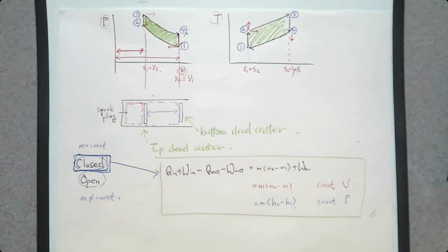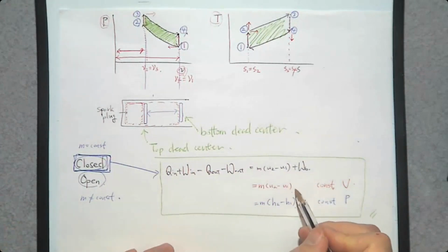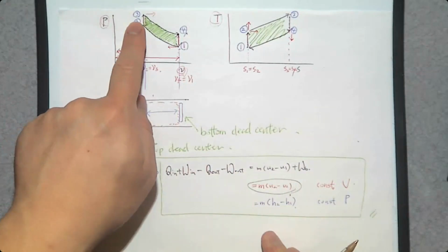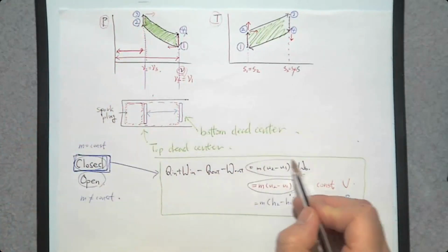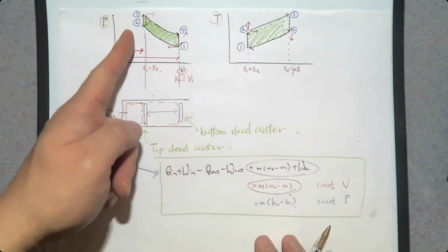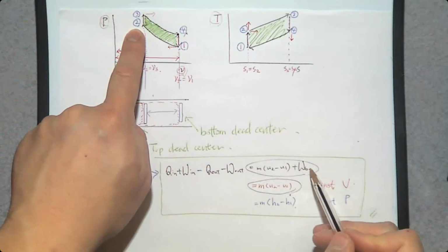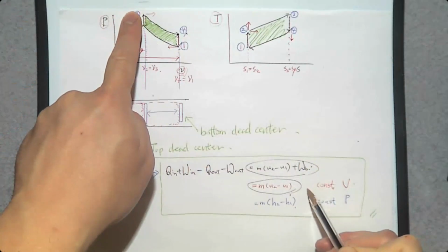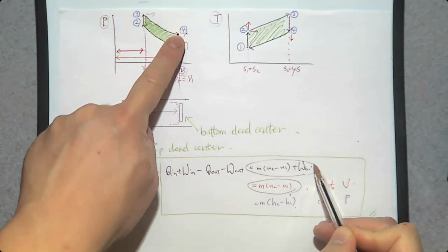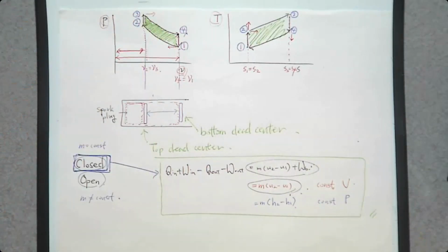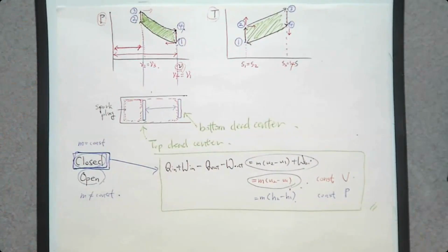So in this case, we have a constant volume process between 2 and 3, and a constant volume process between 1 and 4. So we can use this one for the constant volume process, and this one for the isentropic process. So between 1 and 2 is going to be this one, between 2 and 3, this one, between 3 and 4, this one, between 4 and 1, this one, okay? So based on that, let's find the energy balance equation.